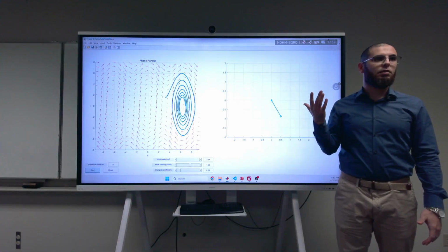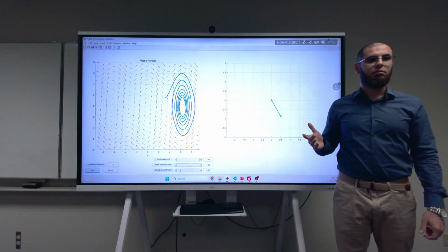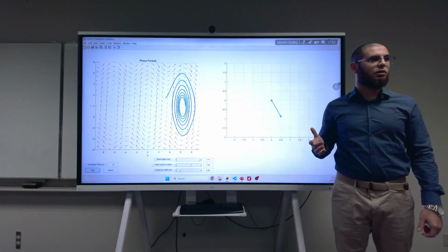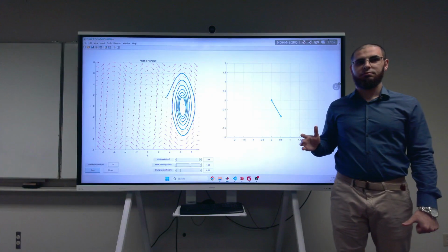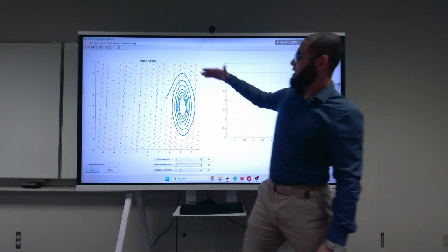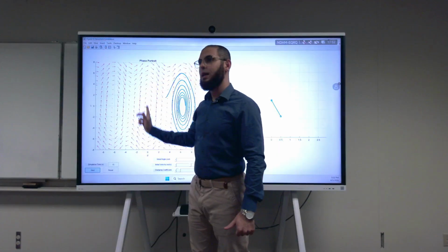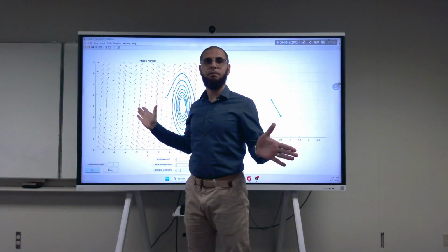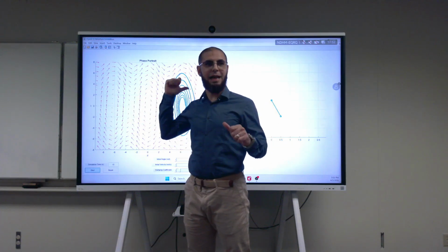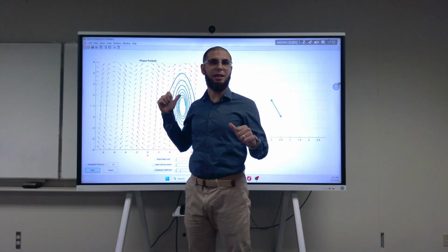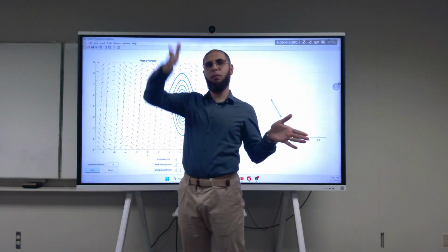Why? Because the true state space, actually, how does it look like? What's it called? Torus. Not a torus. Can you say it's a cut piece of it? So, first of all, when moving in this direction, this is the theta dot, right? Is theta dot from minus pi to pi? No, it's from R. So the torus that you looked at, you remember last time when we looked at the manipulator, was actually theta 1 from minus pi to pi and theta 2 from minus pi to pi.